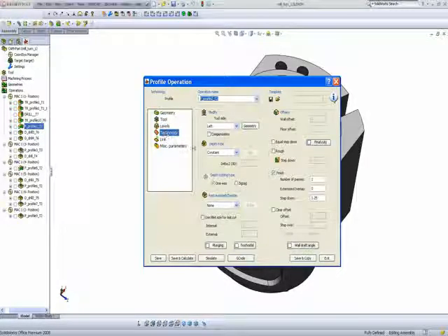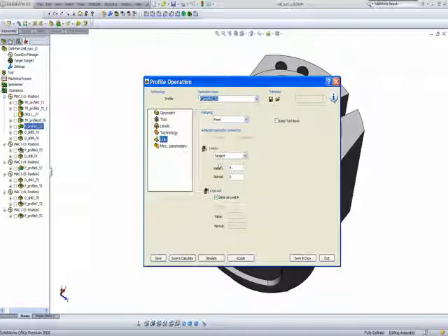And my technology, as you can see, this is a regular milling operation. All the functions that we have in normal milling, we have it here also. Working one way, constant, doing a finish cut only in this particular case, at a step down at 1.25 millimeters. Of course, we have our link in and lead out, both being used as a tangent of 4 millimeters.